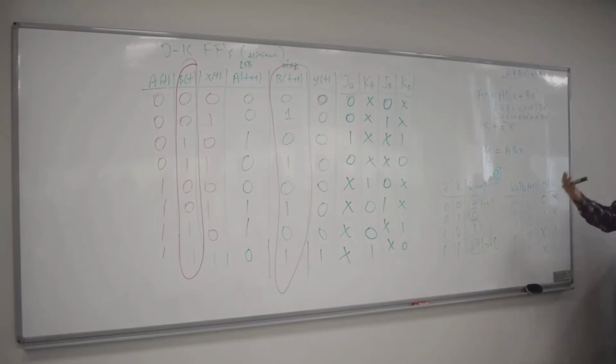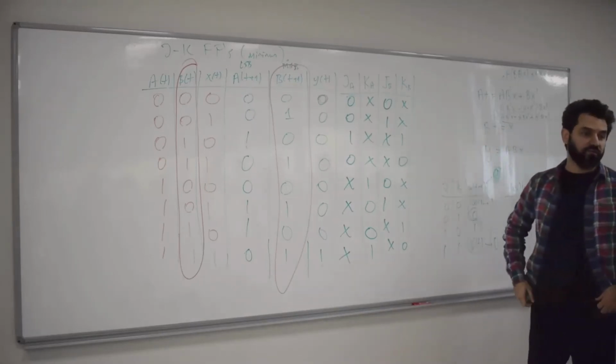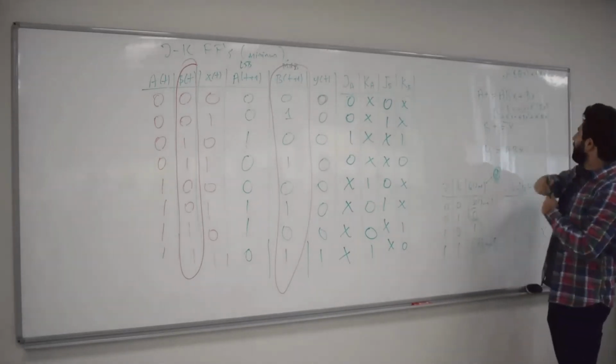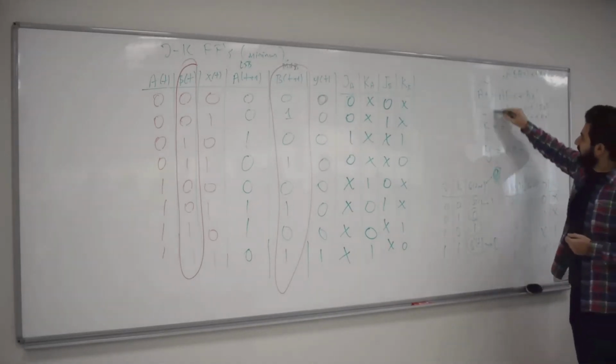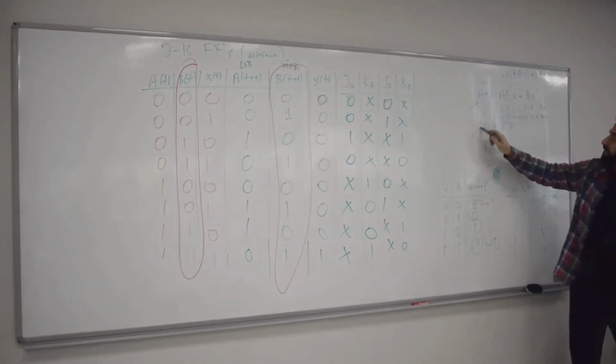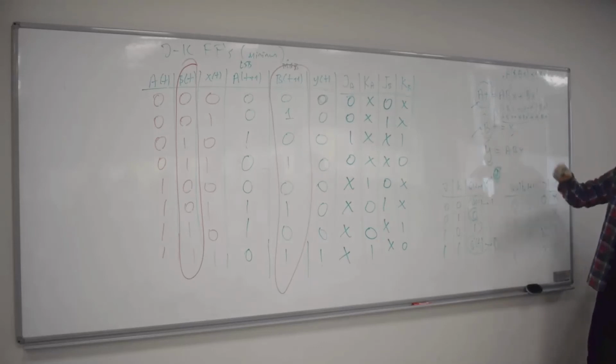However, in order to use them in your design, you have to use these input-output relationships, because the input-output relation is not as straightforward as compared to D flip-flops. Of course, you already have A, B, and Y. If you were to use D flip-flops, you would use these two Boolean expressions to draw your circuit immediately, because a D flip-flop's input is just your next state.